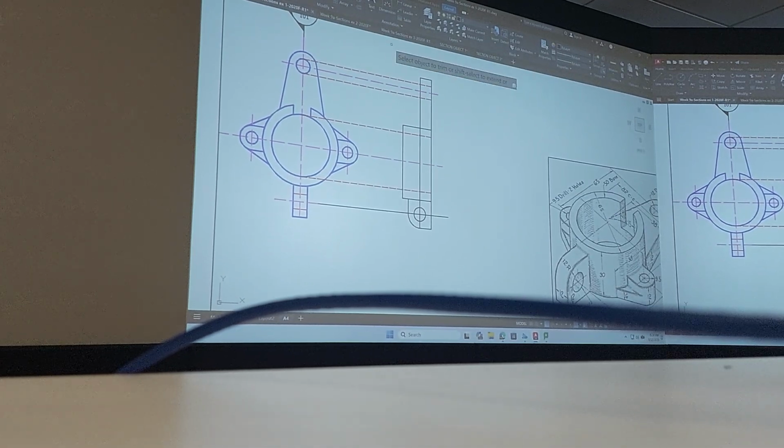I'll take T again, for cutting edge, pick this line here, enter, I can trim these, now you see it's just a hole. I'll do the same thing again, I'll take trim T, pick this line here, and now I can trim these all the way down to there. Yeah, got this.